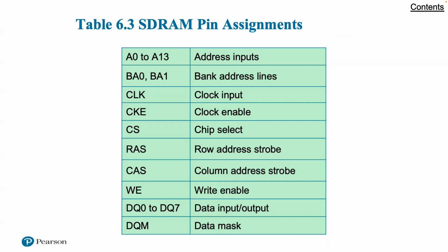In addition, the SDRAM has a multiple-bank internal architecture that improves opportunities for on-chip parallelism. Earlier we talked about some of the studies that have shown that memory accesses tend to be clustered together, and so here we're seeing an architecture that helps along that line.